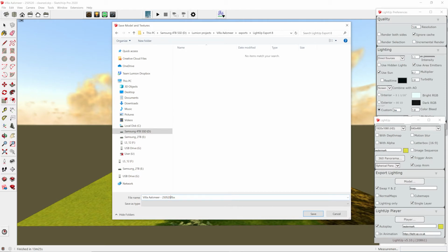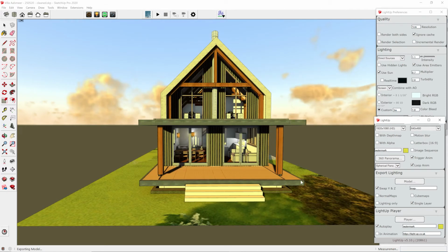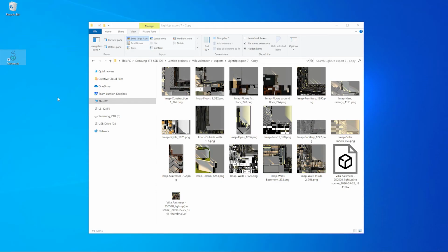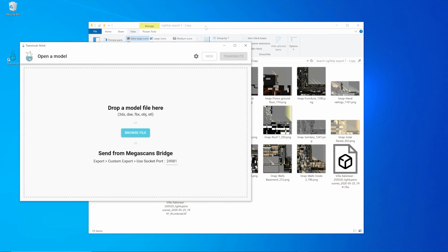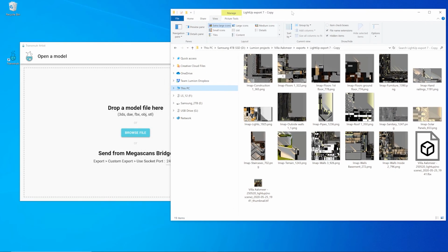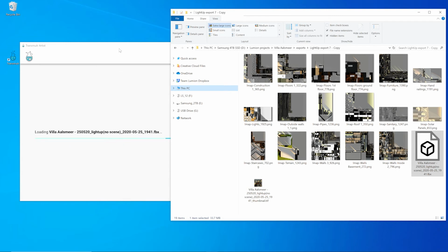And to get the FBX file and its light map textures into the Spoke editor, we need to convert it into the GLB format mentioned earlier. Luckily, one easy method is to import the FBX file into SketchUp again, and then use the GLB export extension.